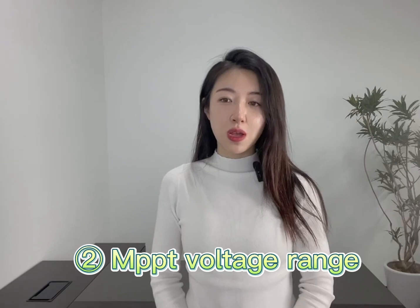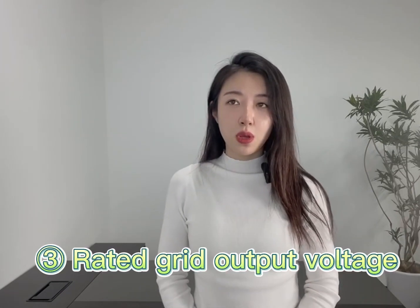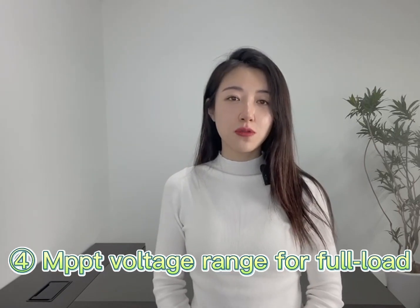If you divide these panels into 4 strings, then your maximum voltage is 5 times 40 volts, which means 200 volts. When the inverter detects the voltage is above the maximum allowable input voltage, it will not start to work. 2. MPPT voltage range. MPPT voltage range means that the MPPT module of the inverter can operate normally only within the DC voltage range required by the equipment. 3. Rated grid output voltage. The AC output voltage should meet the requirement of the local power grid. 4. MPPT voltage range of full load. Within a certain voltage range, the MPPT module can work with maximum efficiency.